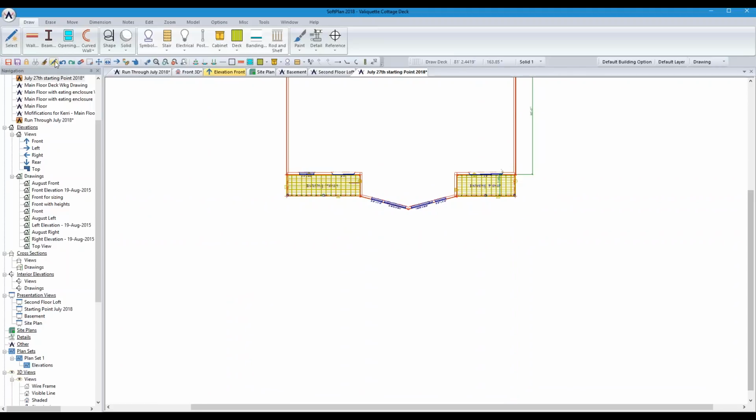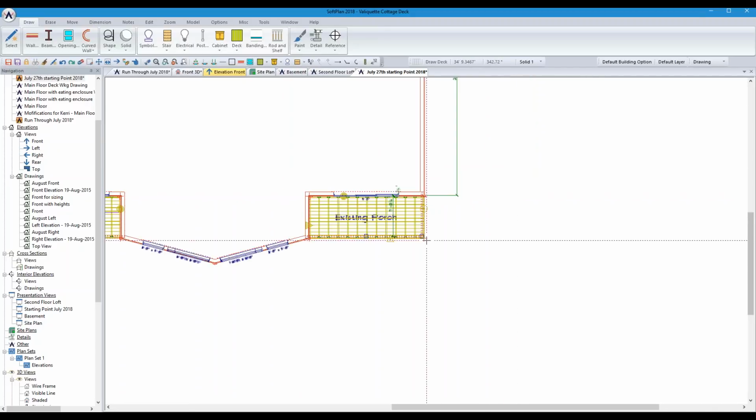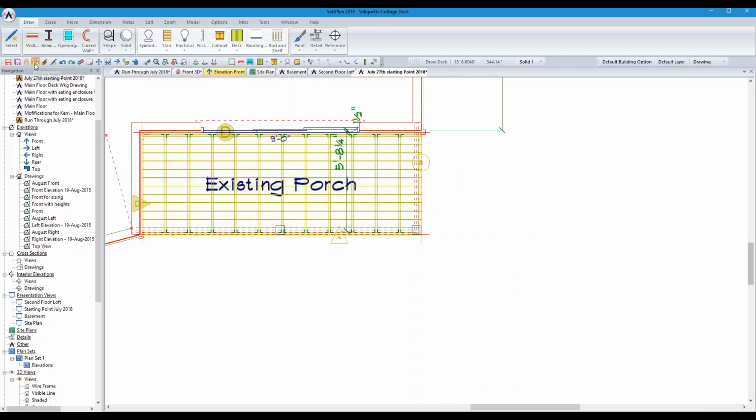Occasionally, you're going to see me use the snap commands as well, which are the fourth icon up here. Also F11 on your keyboard, which allows you to snap to different points. So if I turn it on, you'll see it highlighted in that orangey yellow color, and you'll see projection snaps show up. If you don't like projection snaps, you can turn them off in system options, but we do encourage you to try and get used to using them. What they do is they look for points on an item adjacent to what you're drawing, which will maybe help me to align with, say, that corner when I'm drawing from here. You can see it dotted in, and it helps me to align with that edge.